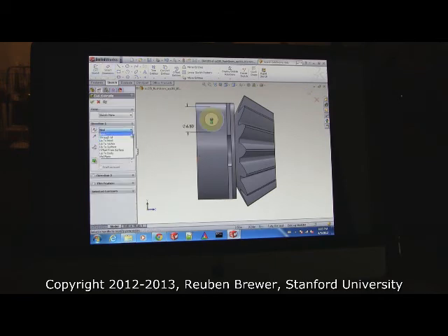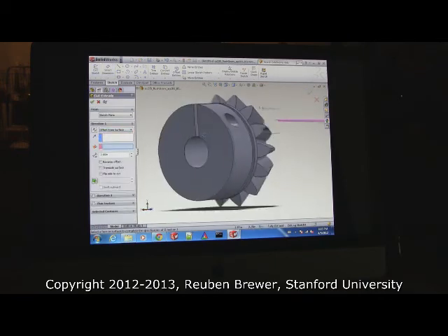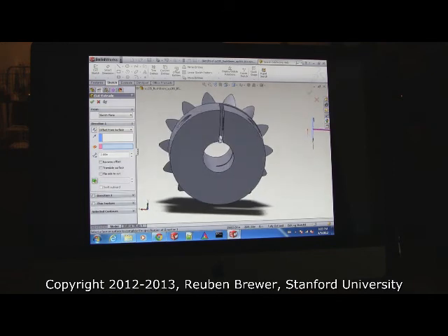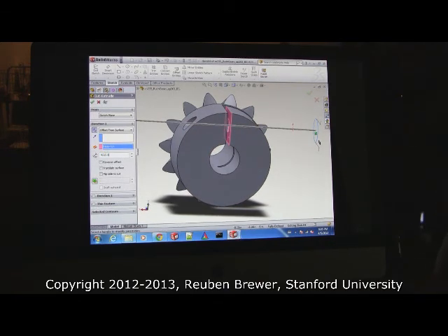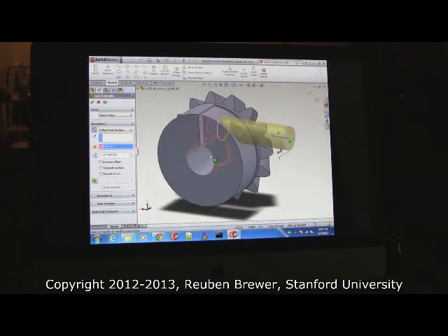And we're going to do an offset from surface. Just one. Offset from this surface here by 4 millimeters. 4 divided by 25.4. Okay, so it should look like this. Anybody know what this hole is? It's for the head of a screw. What did you say, 4? 4 millimeters.